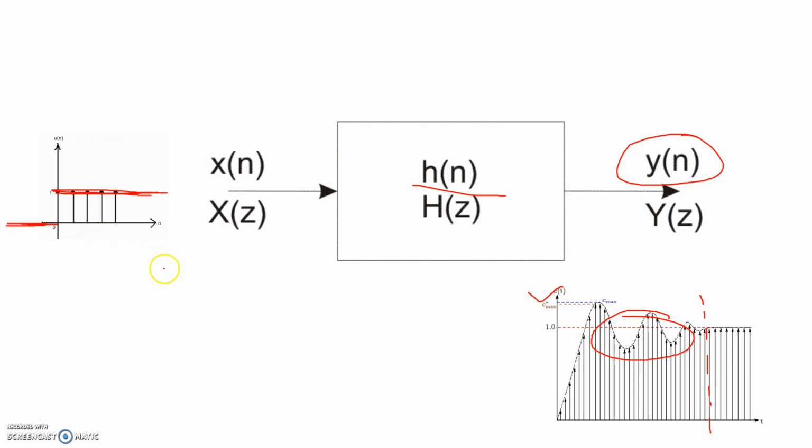Here is an example of a practical scenario. Suppose there is a motor connected to our supply voltage. As soon as you turn on the motor, a very high amount of current suddenly goes to the motor. The current goes from 0 suddenly to a very high value. In that case the motor cannot instantly reach a constant rotational speed.